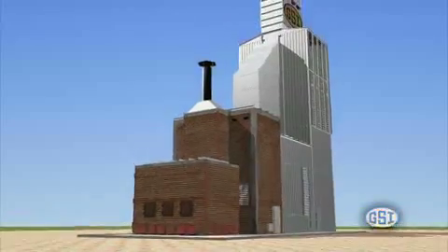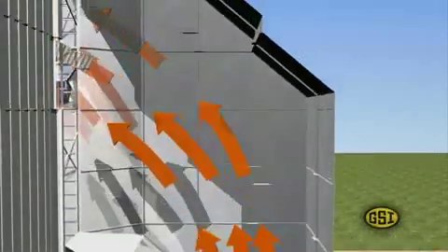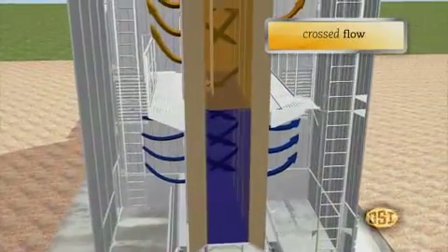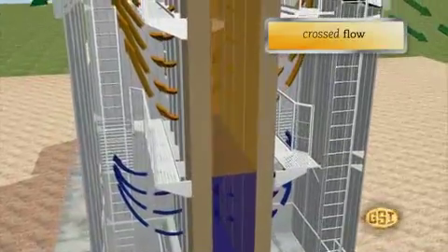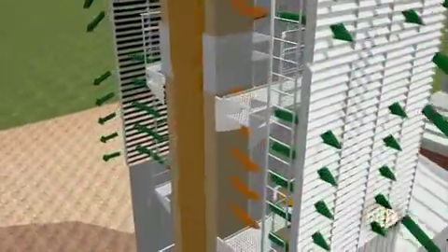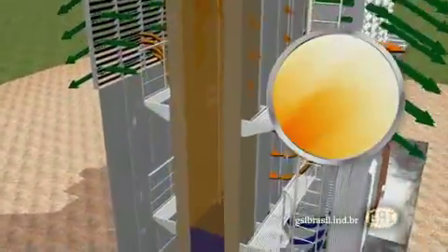Airflow. Hot air enters the process dryer in the upper section of the drying chamber and travels horizontally through the column of grain, perpendicular to the movement of the grain mass. All process dryer models can operate with a cooling chamber in 1/4 of the grain column.